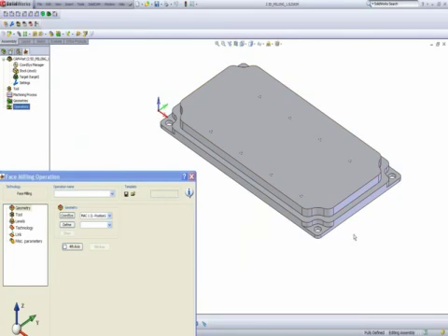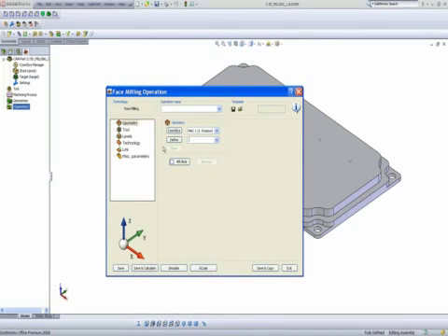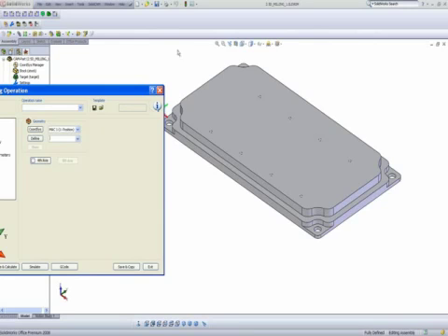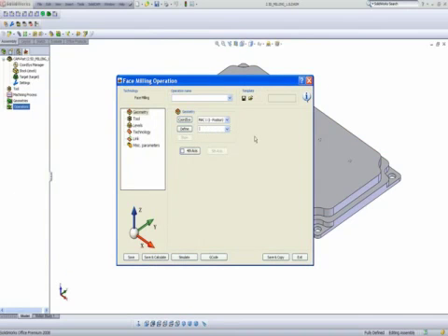That's one option. But there are many times when you're faced with a problem where you may not have that particular tool, and you may have just a regular end mill, say 20 millimeters. So there are different ways of doing it, such as going across, back and forth on the face itself until you cover the entire part. We'll use a second example for this particular part.